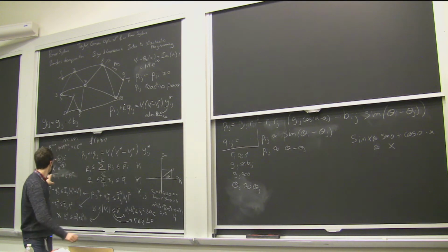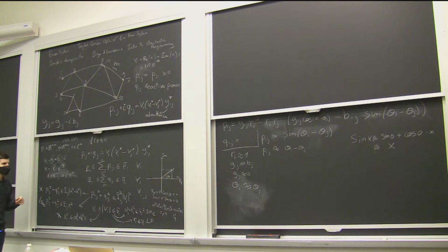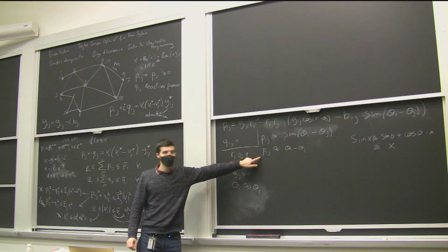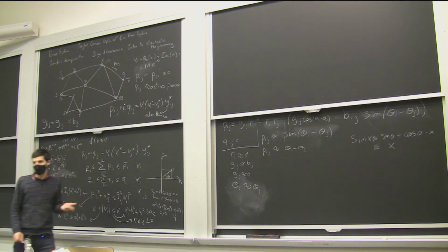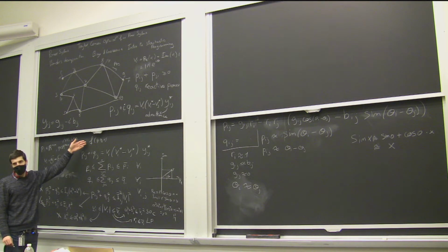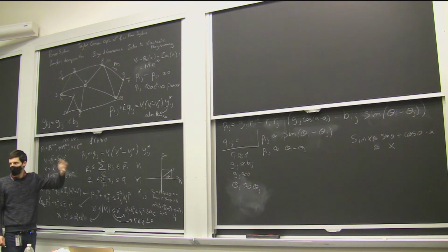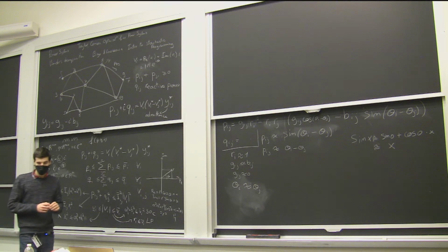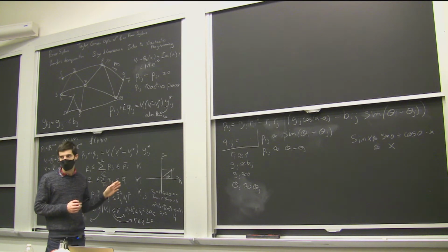Okay, so what is used a lot in practice to solve power systems is to use this representation and then do these approximations such that this constraint becomes this. And now all the constraints are linear. And if the objective is quadratic, it's just a QP. So it can be solved extremely efficiently on extremely large networks. If the objective is linear, it's even faster. Any question up till now?